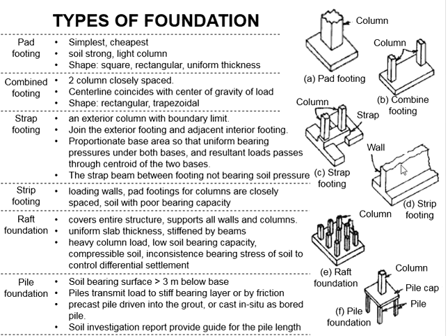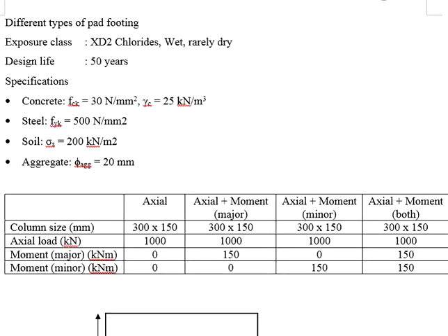We have explained various types of foundations as well as their applications in our previous videos about reinforced concrete design too. To make it simple, under good soil conditions, pad footing may be used, whereas under poor soil conditions, when the soil bearing pressure is relatively low, you will need the pile foundations in order to ensure the stability of a structure. Now for this and the following videos, we're going to first deal with the pad footing.